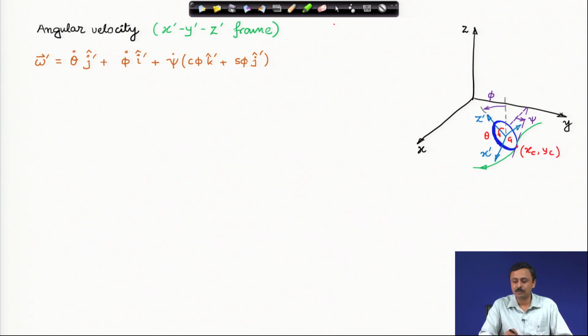The coin is an axisymmetric body. Using that fact, we have set our coordinate system such that the moment of inertia tensor of the coin in this frame is constant. The z prime axis and x prime axis have been chosen very carefully, so that the coin is always in the x prime z prime frame, which has been shown in the figure.